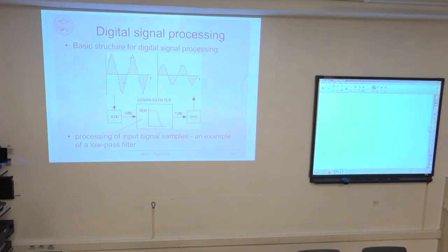And the idea, the simple description of this idea, so you have the analog waveform, this solid line, and we have these dashed vertical lines represent position of samples, and we take only the values in these vertical lines to this AD converter. So we have these digits, we have a sequence x of n, instead of x of t continuous time signal, we have sequence of digits, sequence of numbers. And after this sequence is processed by a signal processor, by some kind of computer, it will create an output sequence, y of n.